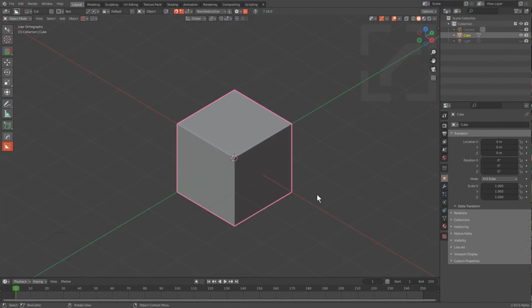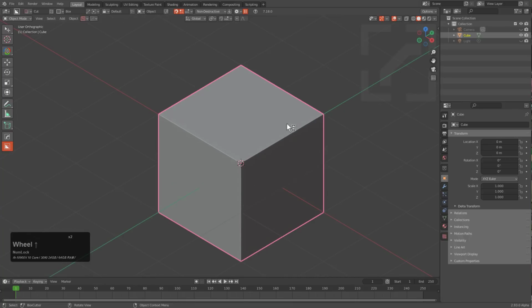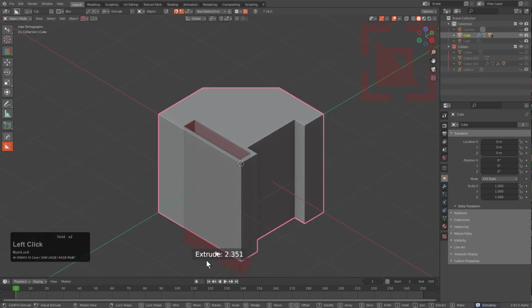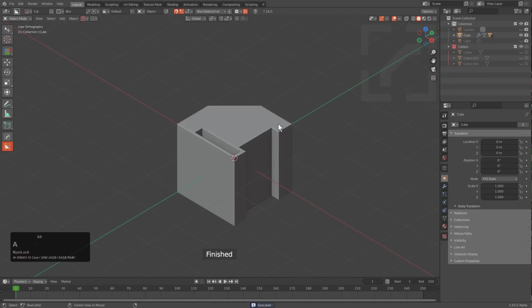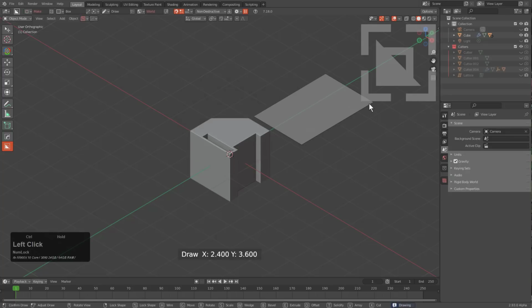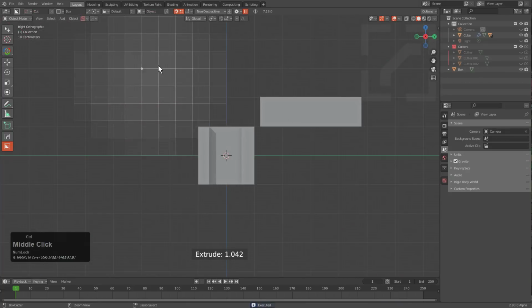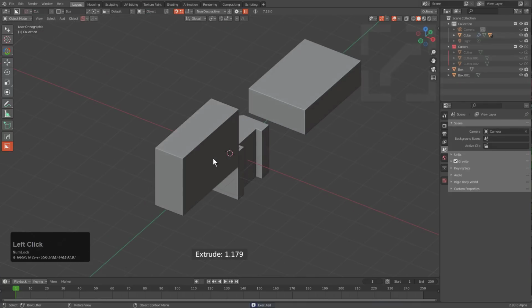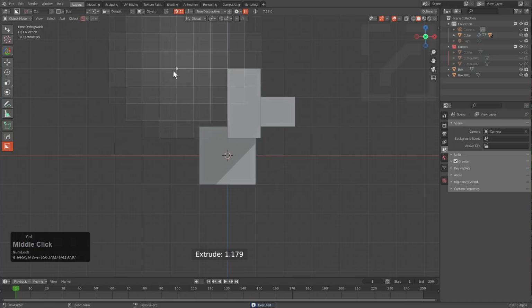And currently I'm using it in Blender 2.93, and if we show it in action, basically I can have grid enabled, and if we just begin drawing, of course I'm able to draw from surface and view just like I was showing previously. I can of course even press G to grab my shapes and move them around. However, if we were to deselect and we bring up our grid, we see that we have our grid oriented to the world. However, if we look at it from the side, like we are now, we also see that the grid now knows to orient itself to the side whenever you're no longer looking at it from front. And the same thing with all the axes.